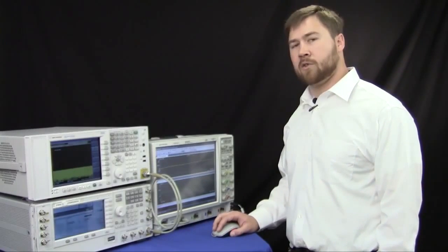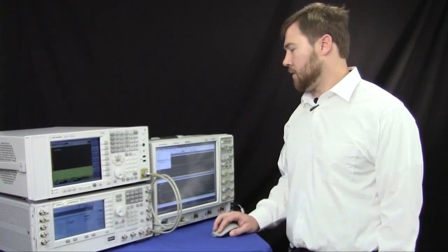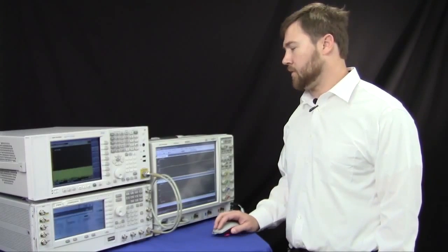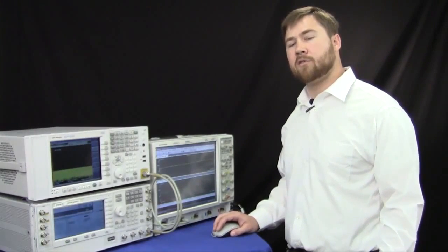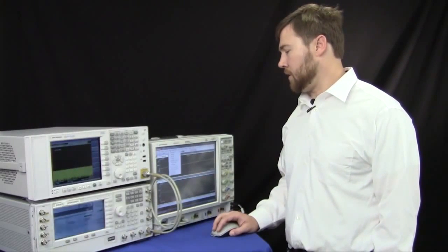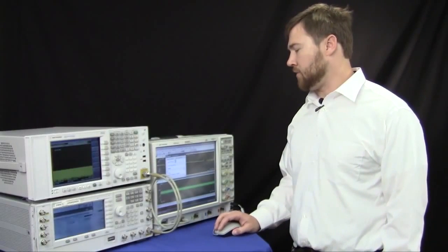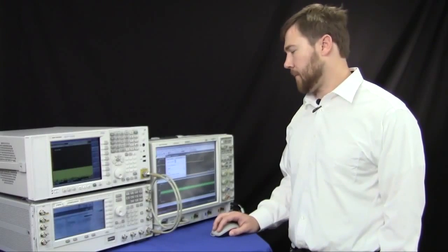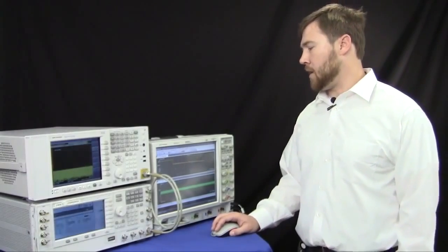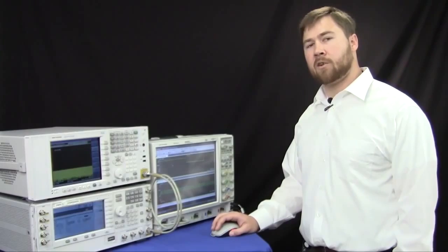And once I'm satisfied that it looks good, I'm going to go back in here into File, Copy Trace, and I'm going to copy this trace into Register D1. Once I've done that, I can apply the trace in Register D1 as a correction. So I'm going to go in here into Input, Fixed Equalization. I've applied Register D1 as a correction. And you'll notice here that the frequency response of the IF is now flat across the full bandwidth.